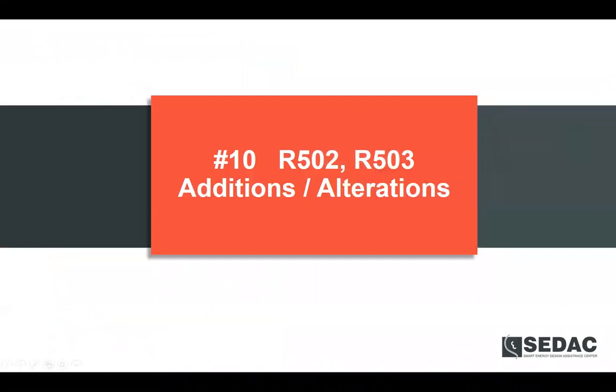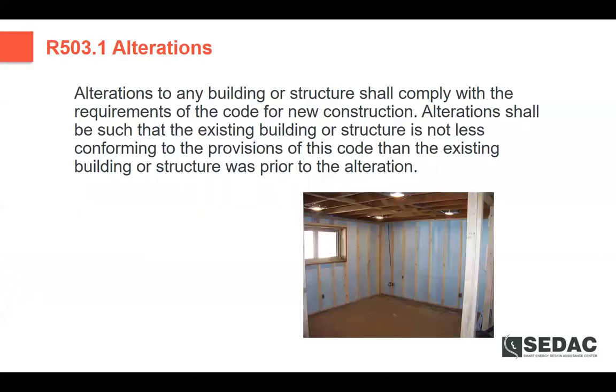So as we get over to additions, alterations, renovations, this is where a lot of the questions and challenges will definitely come into play. We do have several questions here I do see. We'll get to those shortly as we conclude our presentation. But as we get into additions and alterations, this notes that only the alterations need to comply with the requirements for new construction, and alterations should not be less conforming than the existing building was before you started to alter it.